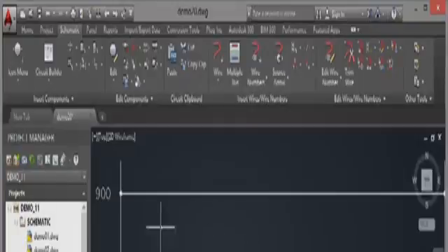Now you'll notice the connectors are left behind. That's because the project properties are set to insert that default connector, so make sure that you delete the connectors as well. Now I'm not going to bore you by deleting every single rung on the ladder, but it's just good housekeeping. Get in there, tidy it up, zoom in. I'll just double click the wheel on the mouse to zoom extents and make sure that all of them have the appropriate spacing. So all these intermediate rungs and connectors you would just delete to tidy up your ladder in your AutoCAD drawing.